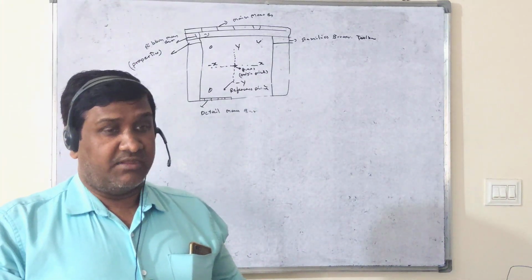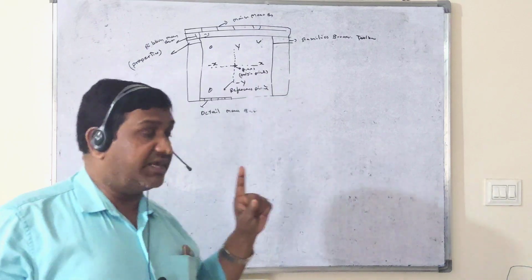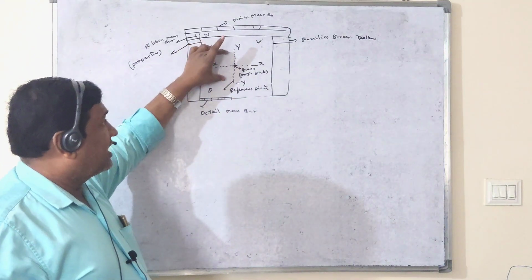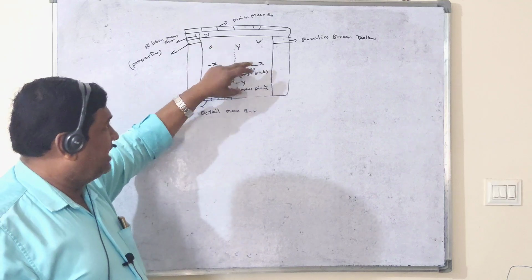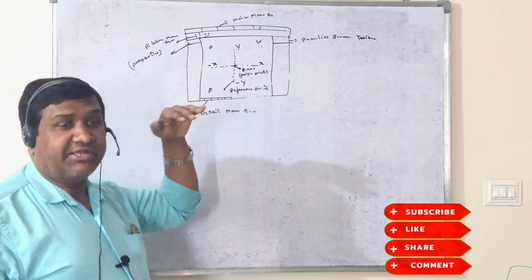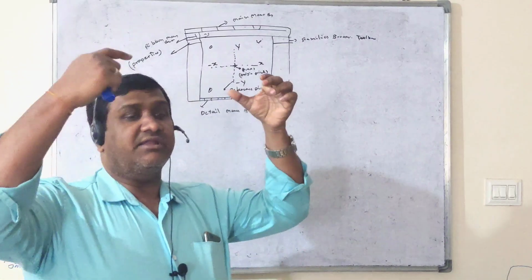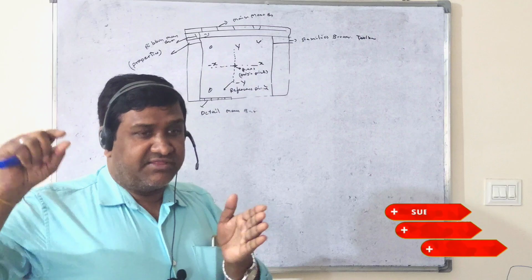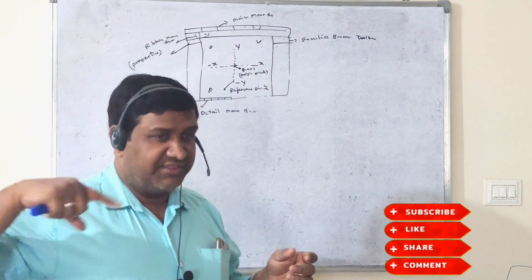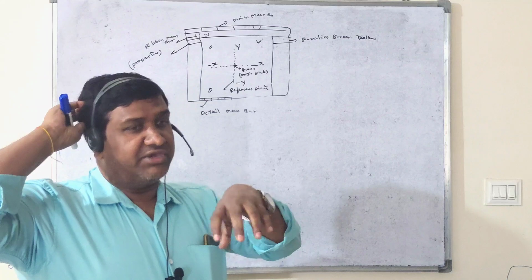Don't do it like that. Each and every family is going to be created with the help of this reference plane only, because it should be exactly the center point of the origin where your family creation is going to happen. Like I already told you, in the project there are north, east, south, west symbols, the elevation symbols.